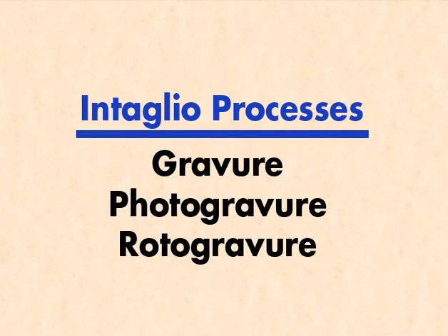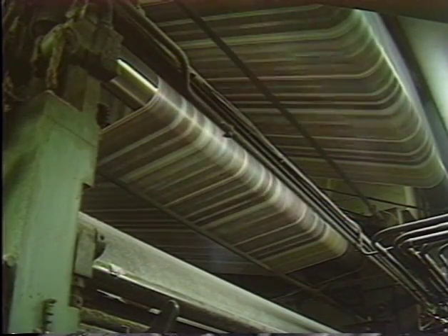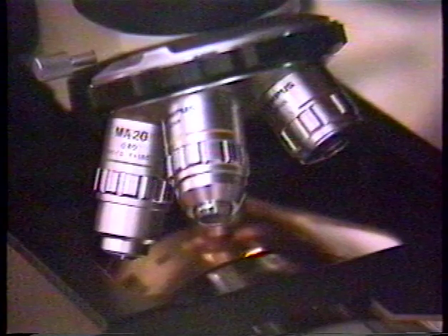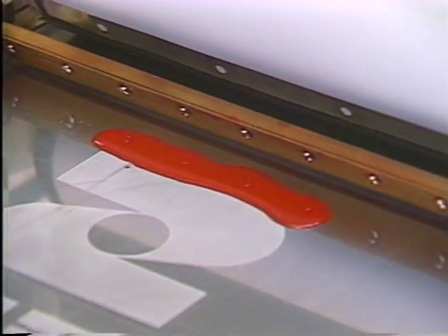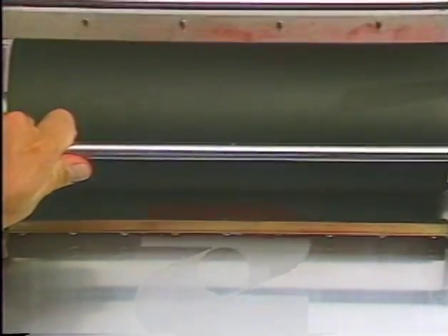Gravure, photogravure, and rotogravure. High-speed commercial gravure printing is accomplished by placing an overall screen pattern on the printing areas of the plate, along with the image to be printed. The supporting structure provided by the screen pattern permits a thin doctor blade to remove excess ink prior to printing, leaving ink in cells etched below the non-printing surface. The substrate being printed removes the ink from the cells.